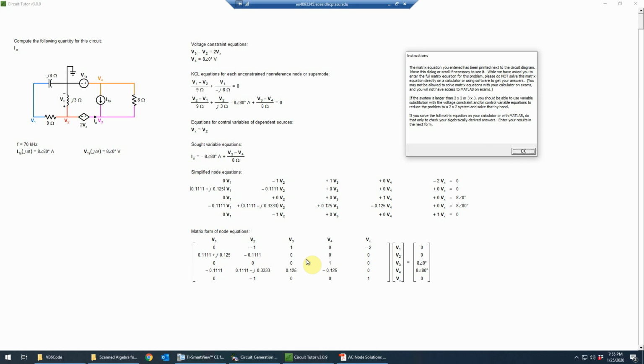And now we're going to proceed to solve these equations. That might look fairly intimidating since we have a 5x5 matrix. I don't really recommend that you do that as a matrix equation because it isn't necessary here. Notice that all the equations other than the KCL equations are quite simple. These two especially can be substituted into the other two, and that'll give us a 2x2 system of equations, which can be solved by elementary algebra. I wouldn't say that full-fledged Gaussian elimination, while it can be done here, is necessary. So I'm going to use elementary algebra after substituting, and I'll do that on paper.